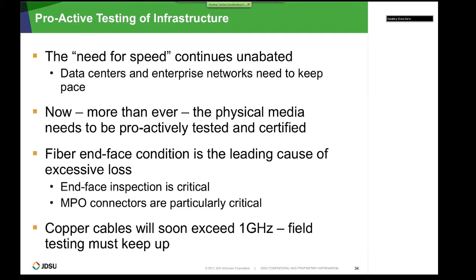The consequence is that this media, I mean copper media mainly, fibers partially, are working at the edge of their physical limits. For that purpose, it is necessary to test very carefully. In the case of fibers, the main issue is contamination, because there is a very limited budget for insertion loss for these fiber lines between data centers, and each contamination adds a significant portion of insertion loss. That's why it is necessary to keep all optical interfaces clean without additional insertion loss.